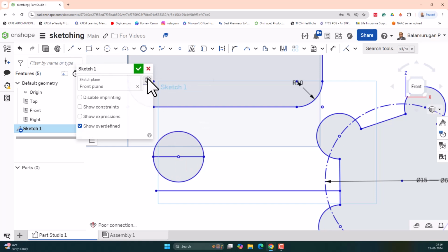If it is an open curve, for example a 3-point arc, which is a single open arc and not a closed curve like a circle, and you want to split this curve, then you can select the split point. Automatically, the curve is split into two portions.